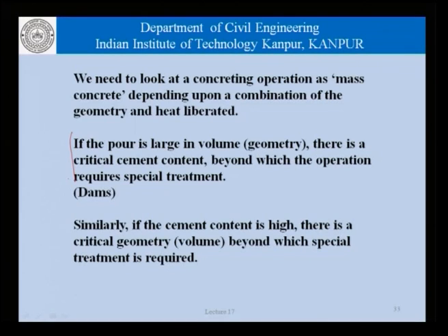We are not particularly bothered about the strength of the concrete, 10 MPa, 12 MPa, I think these are the numbers that we mentioned last time. Similarly, as far as this part is concerned, we are talking about high strength concrete, and in high strength concrete there is a geometry beyond which special treatment is required. In the case of dams, there is a critical cement content which will necessitate considerations of mass concrete to be applied.